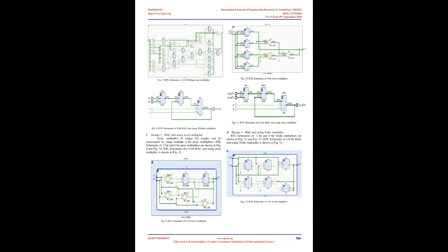It works on the principle of preserving carries until the end. It is one of the widely used circuits for implementing fast arithmetic computations. As the numbers become large, the propagation delay incurred in the ripple carry adder (RCA) and carry look ahead (CLA) adder also increases. Hence, the carry save adder is much faster than conventional adders. The block diagram of a 4-bit carry save adder is shown in Fig 2.